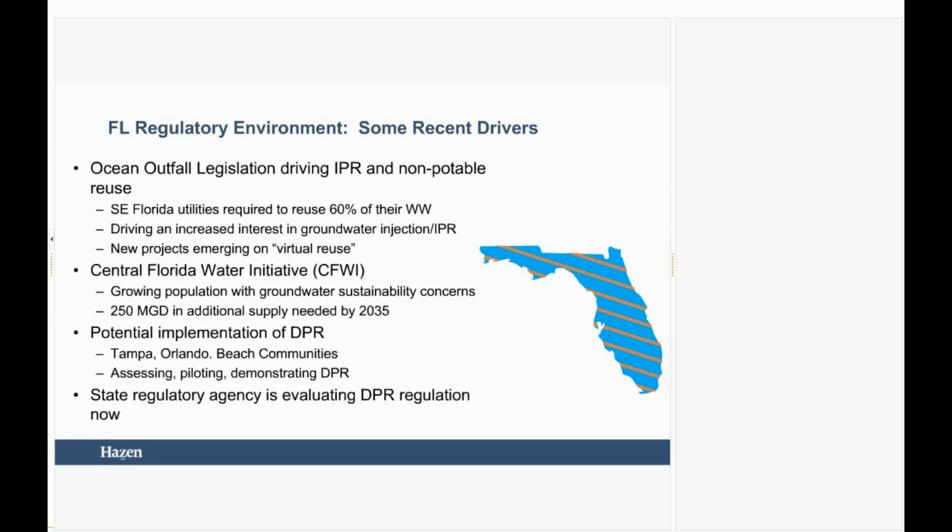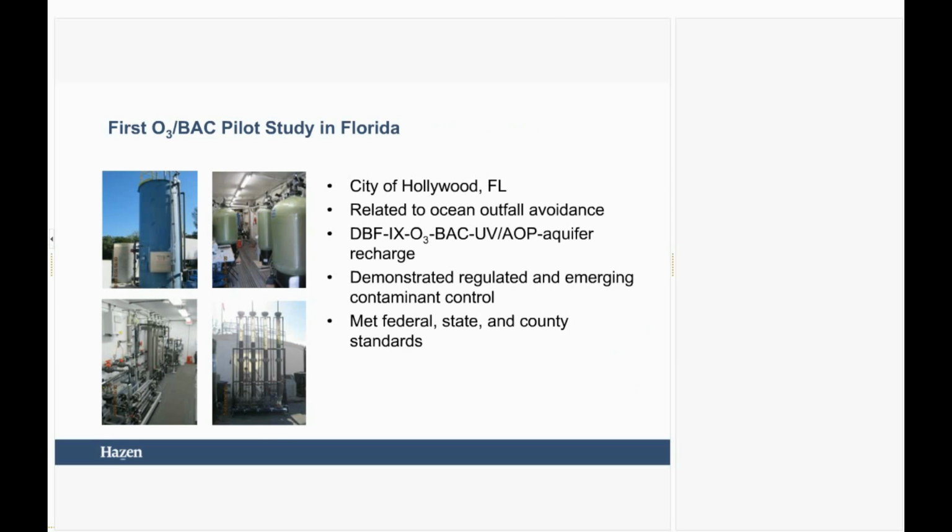There's not a lot of surface water that is captured and stored in that state, so it does use a lot of groundwater traditionally. A lot of work has been done here looking at non-RO type treatment processes. A study here done in the city of Hollywood in Florida, not to be confused with Hollywood in Los Angeles, used a combination of filtration, ion exchange, ozone, BAC and UV for aquifer recharge, rather than going through a reverse